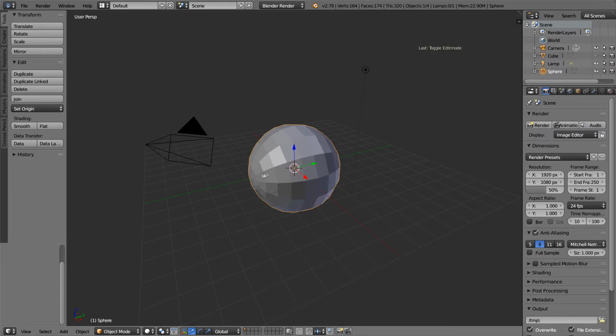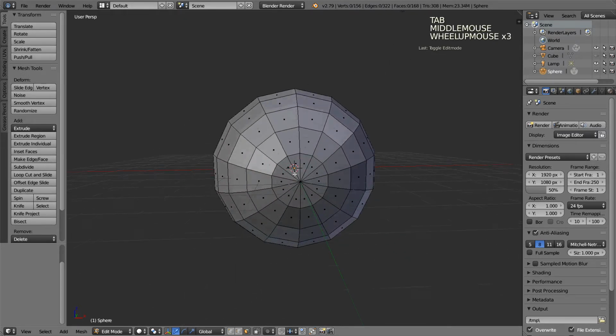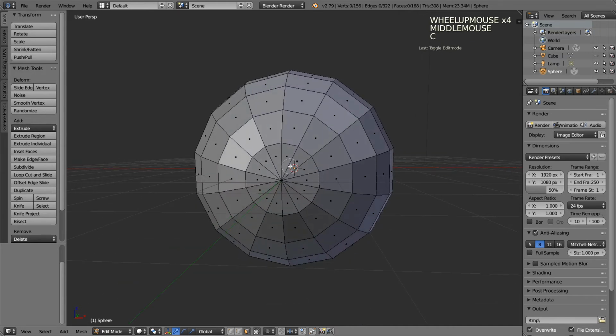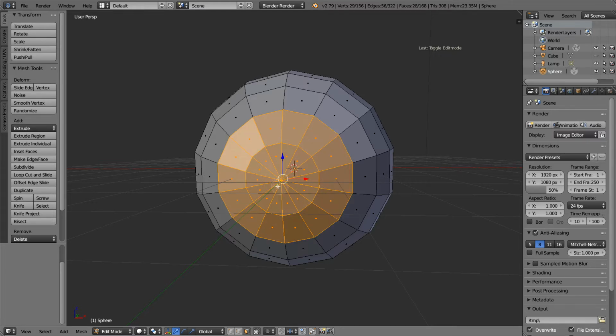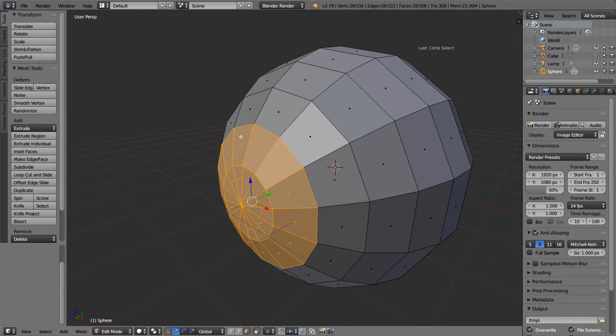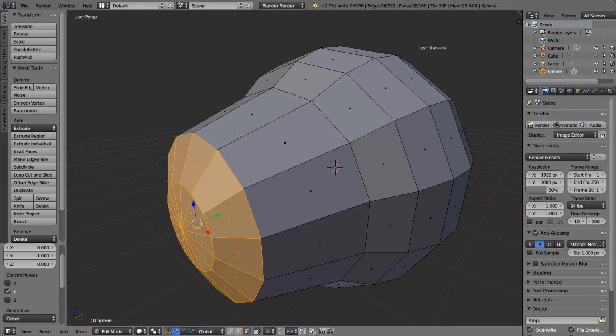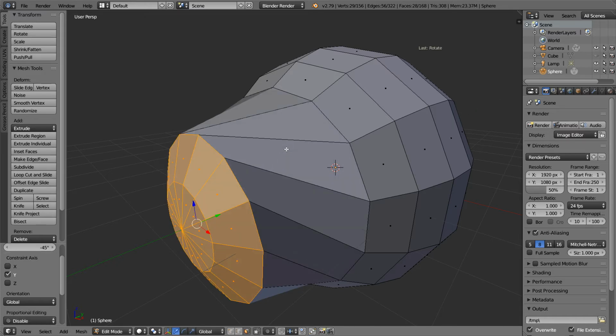If you enter edit mode by pressing tab, and you come up to the object and you press C and then left click, this will allow you to drag this selection over as many faces as you want to select them. You can also move these faces with the same level of precision by pressing, for example, G and Y and typing in the number. In this case, let's type -1. You can do the same, of course, with rotation. Let's hit R and on the y-axis -45.